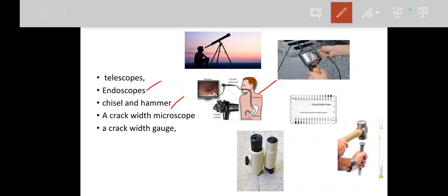Under that, what type of crack has formed, only then can we identify. Suppose you consider a first floor where a tile is laid. We don't know what type of failure has happened to that first floor slab. It may be due to a structural crack or some shrinkage cracks. To identify it correctly, we have to break it and see. A false ceiling is also the same type.